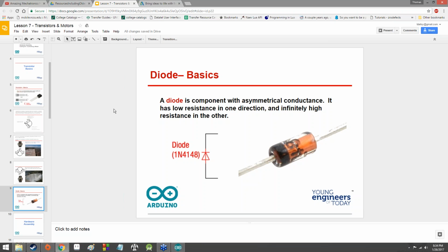A diode is the same way, except it just doesn't have a handy indicator, in that it doesn't light up if you have it hooked up the correct way. A diode will simply just break your circuit if it's not hooked up the right way. So that's another thing to check out. If you have a circuit that has a diode in it and the circuit isn't working, check and make sure the diode is plugged in properly.